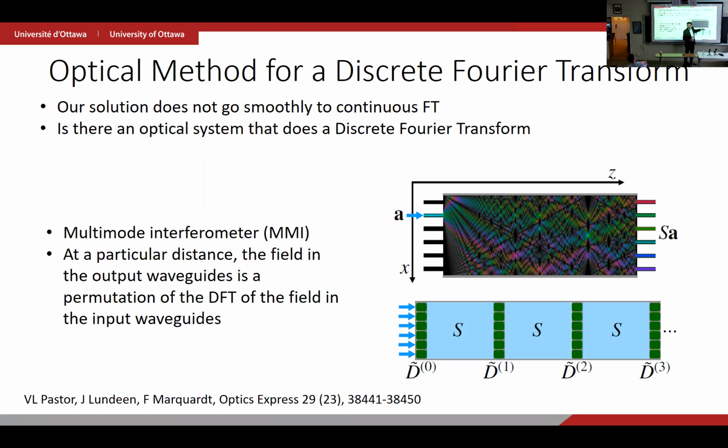Those are going to define the spacing here. That's independent of A. So you have to choose the spacing to match something to do with the width of the waveguide, and you also have to choose the length to be the correct length, which is half of the full self-imaging length. So then there are other lengths at which I'll get any other integer number of points.